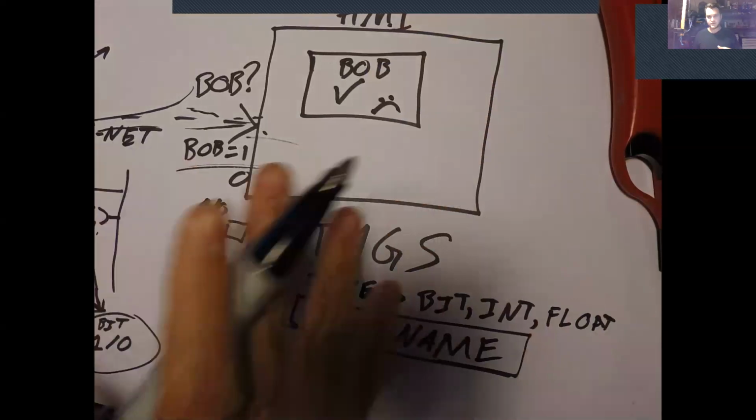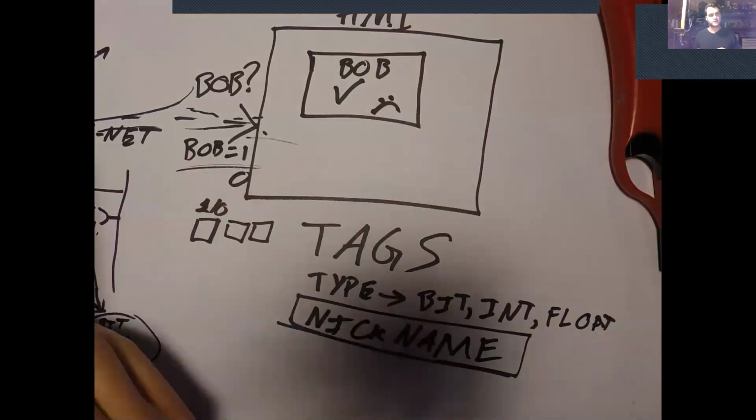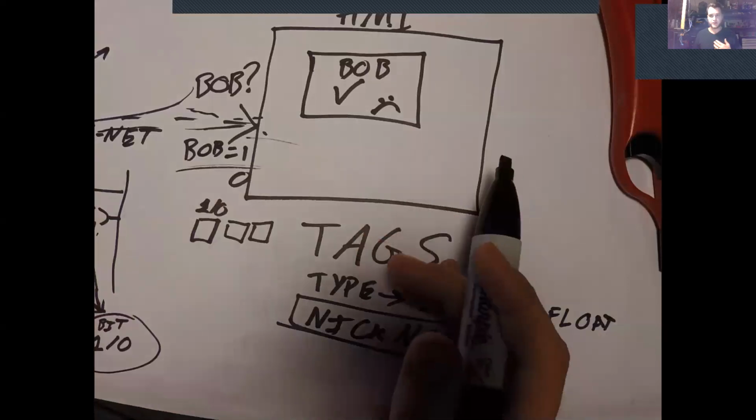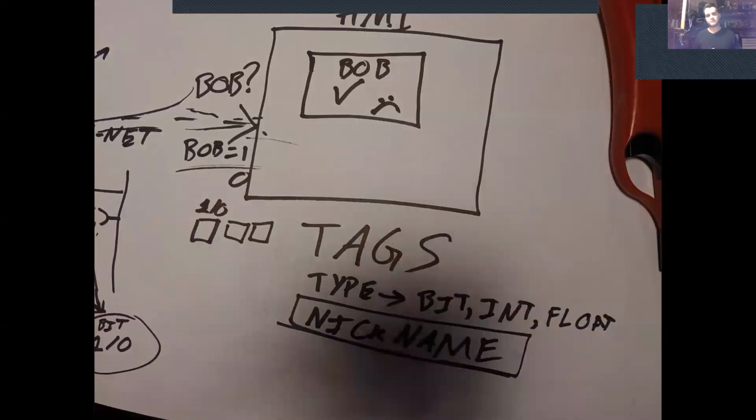And so that's really all we're doing is opening up a new way to access memory in the PLC. And we're also opening up another input point to the PLC that allows us to really start putting in more detailed information other than just a 1 or a 0.